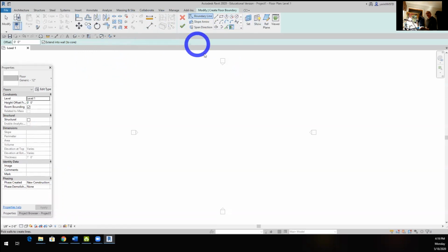This is what it does. It puts you in a sketch mode. What does it mean by sketch mode? It means you cannot do anything. See, I'm going to go ahead and it doesn't do anything. I click my mouse, nothing happening. That means you have to select one of these options here to make the sketch. You can use a line sketch, you can use a square sketch, you can use a circle, whatever you want. So if you want to draw your floor, whichever way you want to do it.